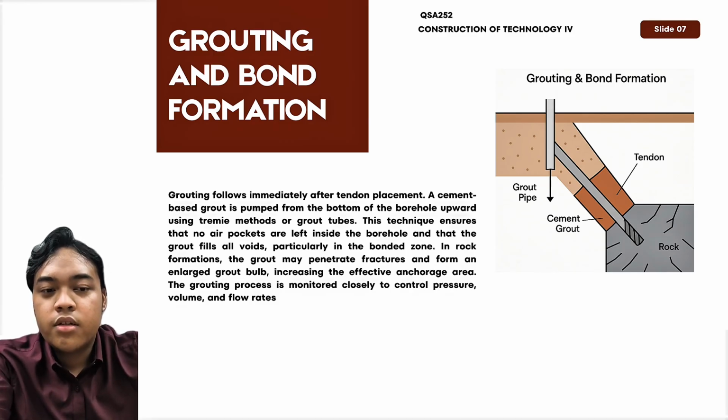In rock formation, the grout may penetrate, fracture, and form an enlarged grout bulb, increasing the effective anchorage area. The grouting process is monitored closely to control pressure, volume, and flow rate.